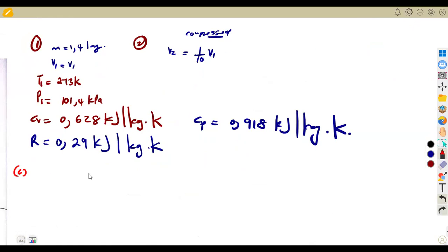We had pressure and so forth there. Here we are limited, we do not have P1 and P2. Remember, P1 V1 to the exponent gamma is equal to P2 V2 to the exponent gamma. If we were given P2, we could use our formula to make gamma the subject, but we do not have it.